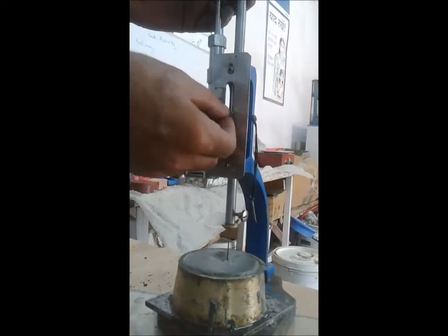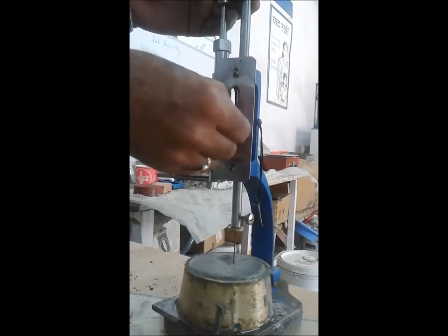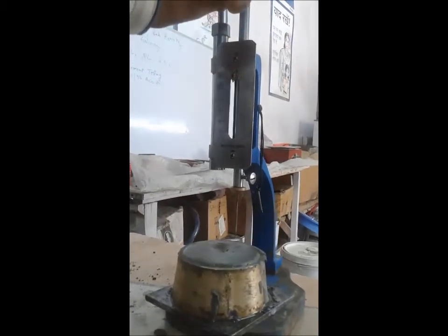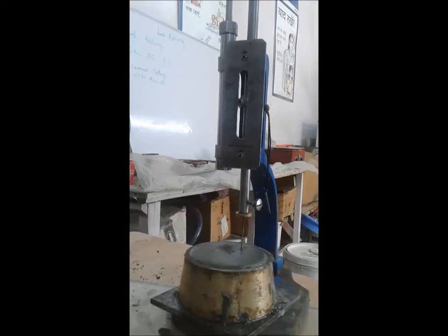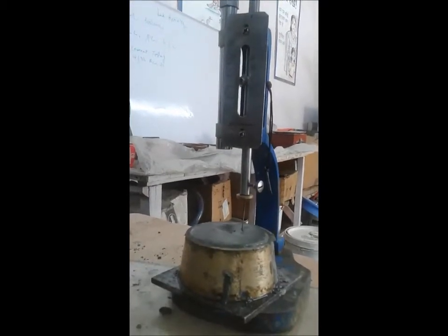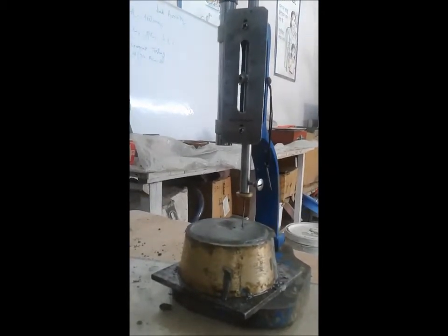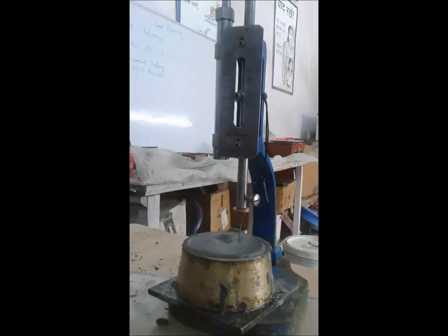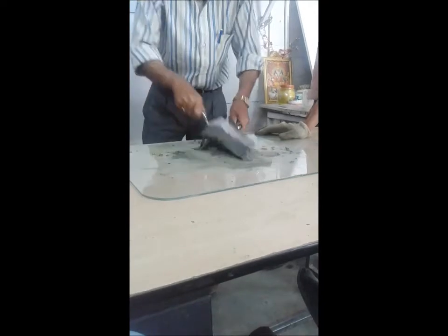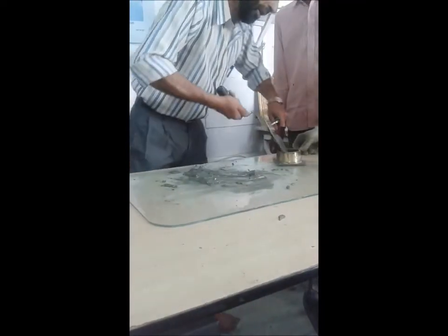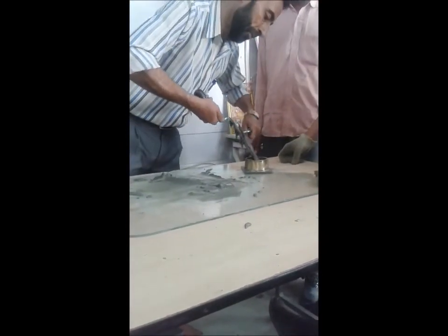The penetration time of the needle in the cement paste should be noted on the gauge. It is repeated at every 2-minute interval and continues until the needle stops at 5 mm above the bottom of the mold, and this time T2 should be noted. The recorded time in any case should not be less than 3 minutes, not more than 5 minutes. Now we find the initial setting time as T2 minus T1, which is about 125 minutes in this test.